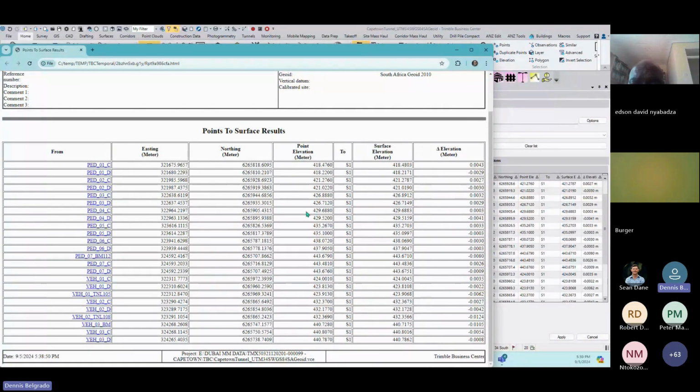So I guess you can see, shown on the right hand side, all these numbers that correspond to the difference between the actual point itself and the surface model, which is the point cloud, essentially. So it's all within, well, except for this one here, around 1 centimeter, 1.2 centimeter.